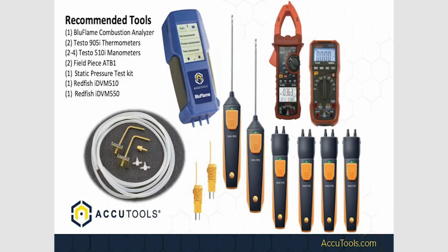It's hooked to a distribution system to get the air out where it's got to go. It's got a ventilation system. It's got a gas supply system, right? There's things that happen. You're standing down there, if you're not watching your incoming gas pressure, how many of you guys have seen furnaces lock out on intermittent flame failure, right? You go out there and you clean the igniter and you do all kinds of other things.